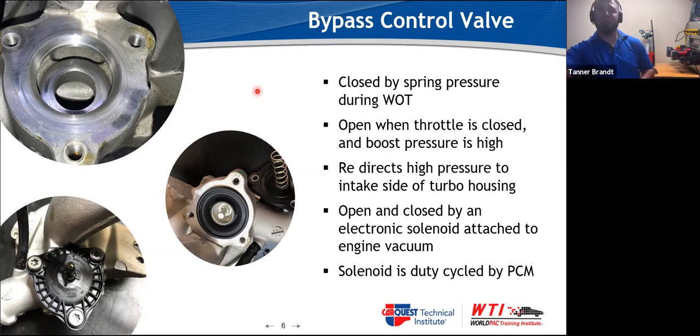One thing to note, this is on a Chevy Cruze here. There's a lot of Cruze stuff in here because we have tons of issues with these. This will relate to any vehicle that has this. This one had oil in it. We'll go over the failure that causes this on any turbo. If a turbo has oil on the intake side, it can sit down here and pull into this.